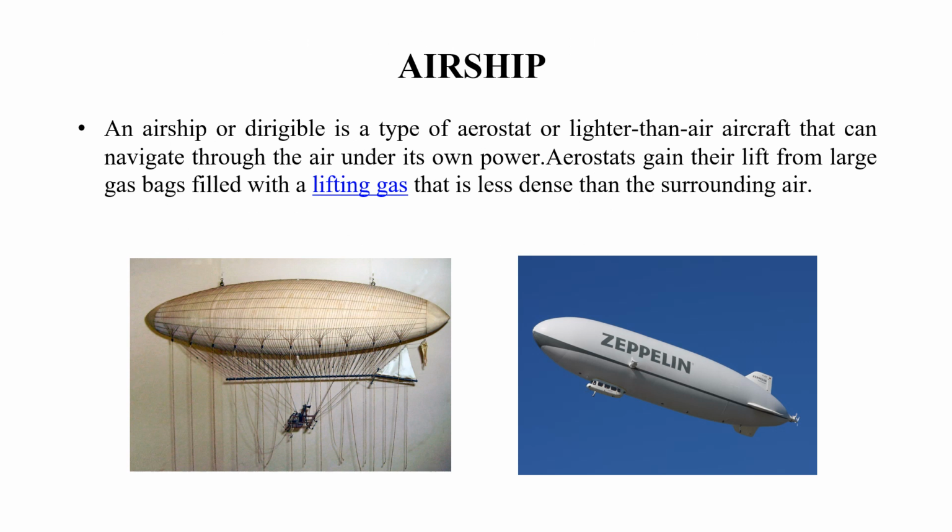The next is airship. The airship is dirigible, and it's a type of aerostat or lighter than air system that should navigate through its own power. Aerostats gain their lift from large gas bags filled with lifting gases like helium or hydrogen, which is less dense than the atmospheric air. That should provide lift to the device.